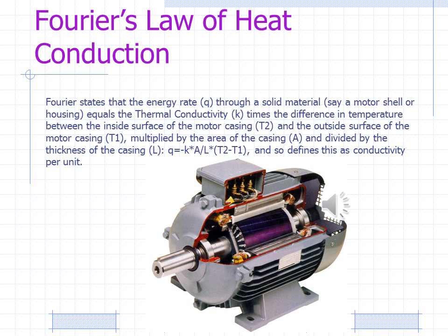So there's a lot of entropy going on at each step, which is okay in this process, but the internal heat of the motor builds up. So many things go on inside the motor, and many designs of motors are available. You can't give the internal temperature based on knowledge of the outside temperature. If you're lucky to find an open motor design, you may see temperatures of the stator coils up to 150 degrees C, and not much of an increase on the outside of the motor casing.